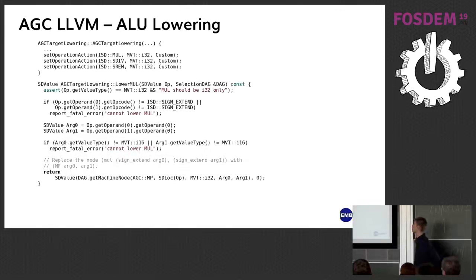Divide, whose implementation isn't on the screen, takes one double word numerator and a single word denominator, and produces two single words, a result and a remainder. So it matches either a divide or a remainder with a sign extended denominator, and the output is a sign extend.